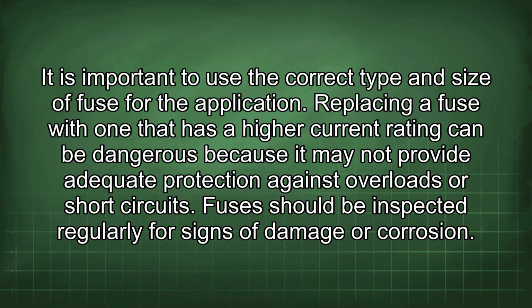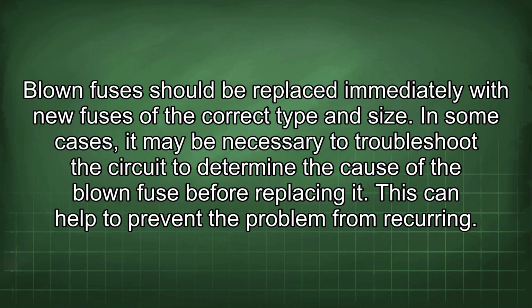Fuses should be inspected regularly for signs of damage or corrosion. Blown fuses should be replaced immediately with new fuses of the correct type and size. In some cases, it may be necessary to troubleshoot the circuit to determine the cause of the blown fuse before replacing it. This can help to prevent the problem from recurring.